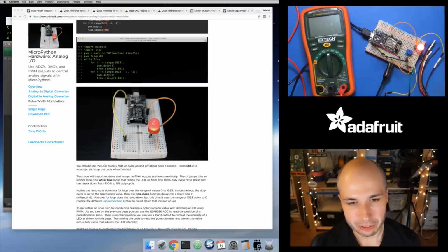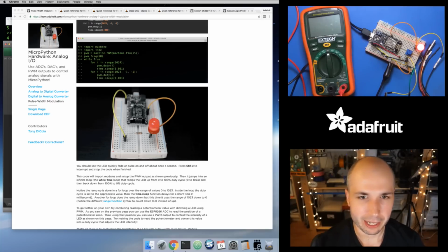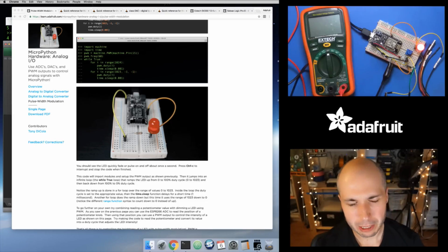It's an external analog to digital converter, so you'll have to connect it to your chip. And hopefully in the next few videos, I'm going to be looking at how to talk to SPI and I2C devices. I can't remember which one. Most ADCs are SPI devices, I want to say, just because usually they're sending data really quickly. So in that case, you'll have to implement the protocol that it has. Usually you're reading a register from the ADC that has the sample values. But that'll probably be an example that I do in the future, of looking at an external analog to digital converter. And the ADS1115 is a nice one.